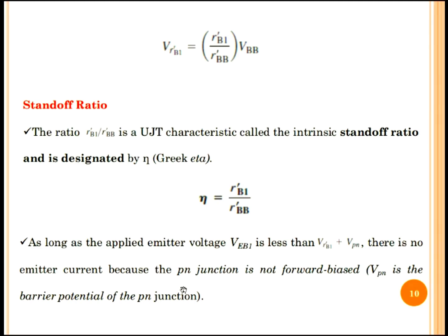If you form a PN junction diode, intrinsically there will be a built-in potential. We call it VBI. If you have worked out the problem which I gave a few classes before, you will remember. That VBI, the potential barrier or built-in potential, dictates the threshold voltage or knee voltage, whatever.